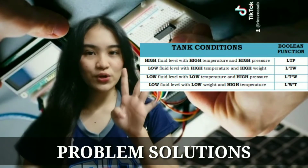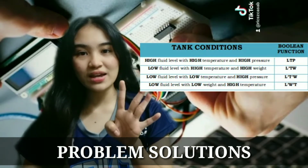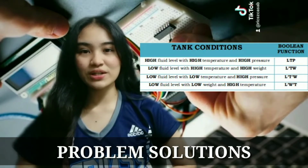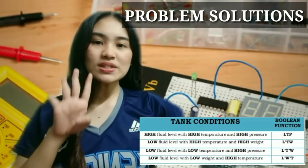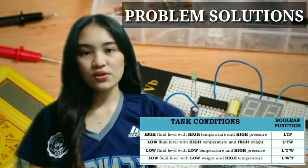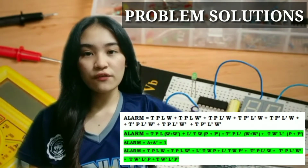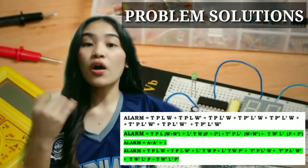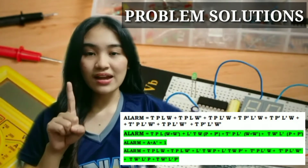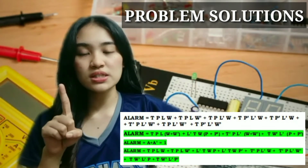So that's the 4 conditions with the 4 Boolean functions that we need to satisfy for the alarm of the water tank to work properly. Using those 4 Boolean functions that satisfy our water tank conditions, we will be deriving 8 Boolean functions, which are a combination of the 4 parameters. And after that, you have to take note of those 8 Boolean functions.